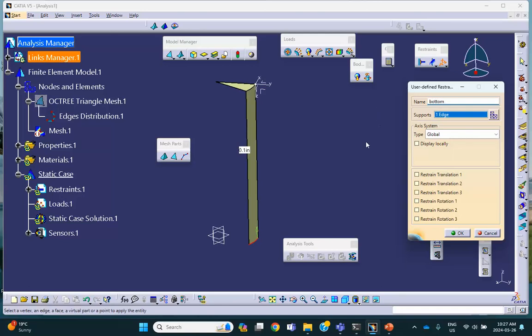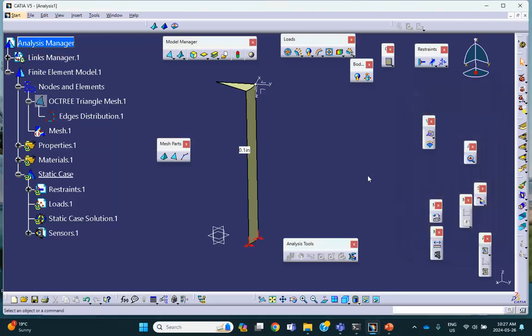And this is in the XY planar symmetry. As soon as you say XY planar symmetry, no Z translation, and rotation's exactly the opposite. Good. Now let's do these two edges.